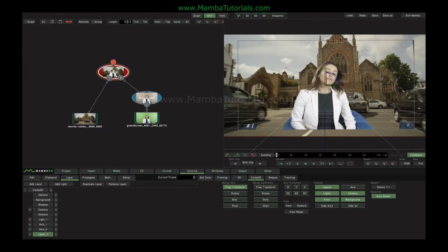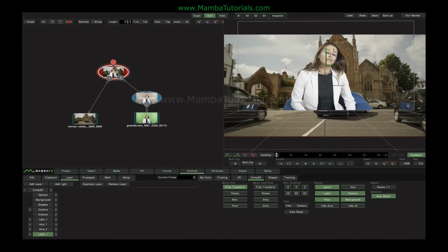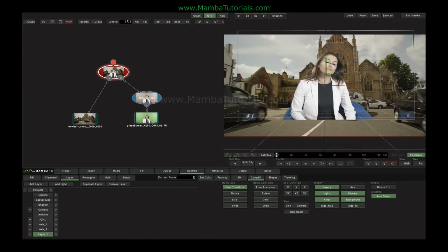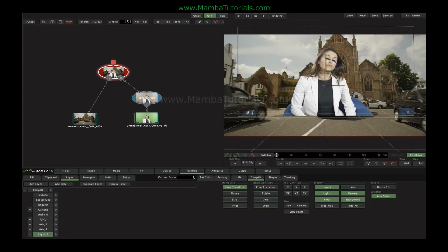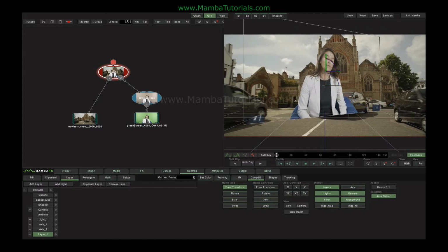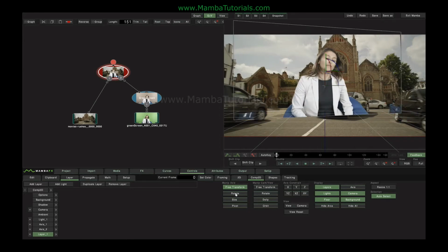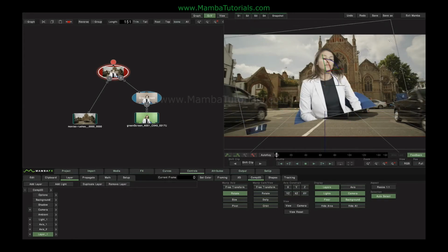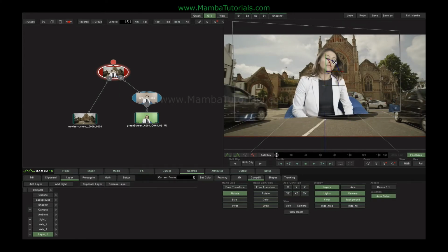The axes lines here can also be used to restrict movement by holding down Shift. So I've now got Shift held down and selecting the Y axis only, you can see that I'm making a movement constrained to only Y movement. Combinations can also be used, so Shift and Alt will now only rotate in that axis. Alternatively, we can pick one of the restricted manipulators, so now just with the left button only without any modifiers, I'm now making rotational changes.